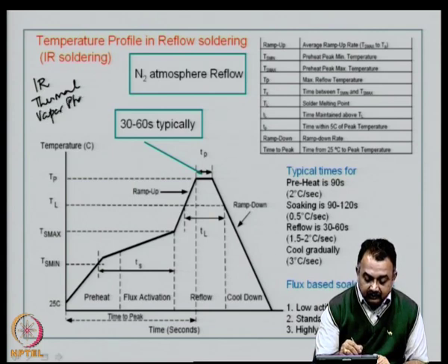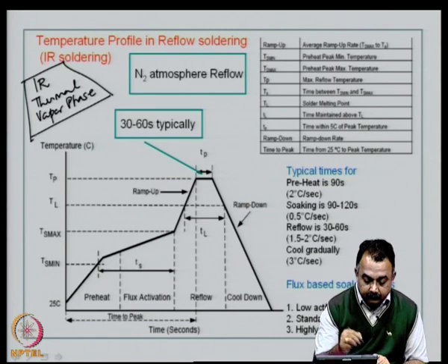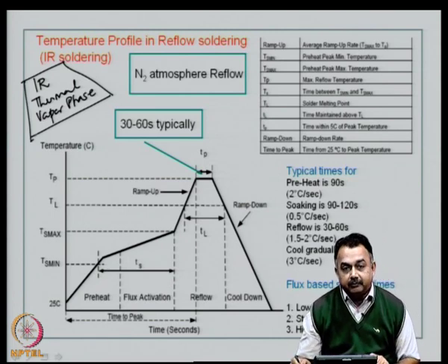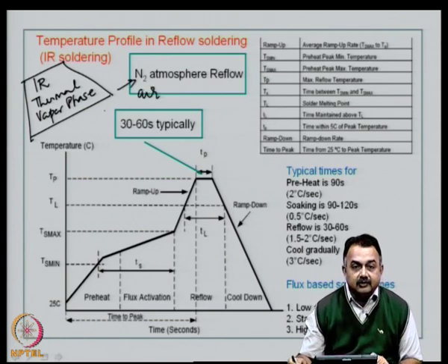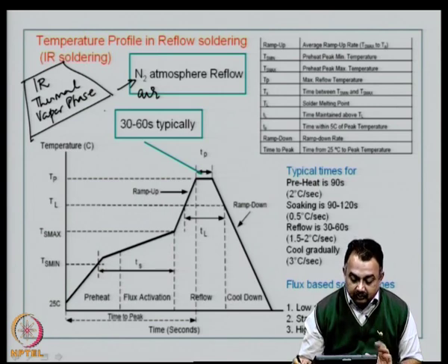We have seen all these three types of reflow soldering processes. Now, the atmosphere for reflow could either be just air or it could be done in nitrogen atmosphere. The influence of air or nitrogen in the reflow process goes with experience and with a careful study of the components that are used and the solder paste materials that are being used.